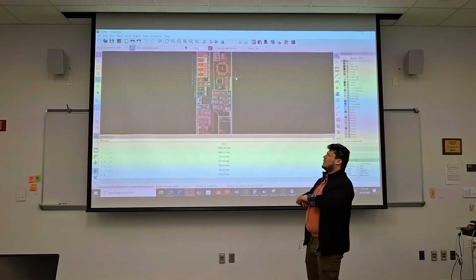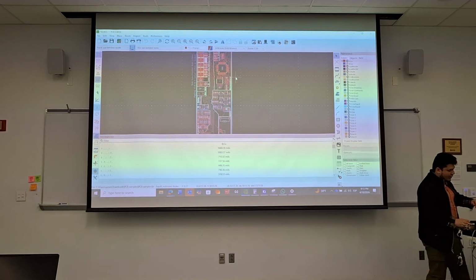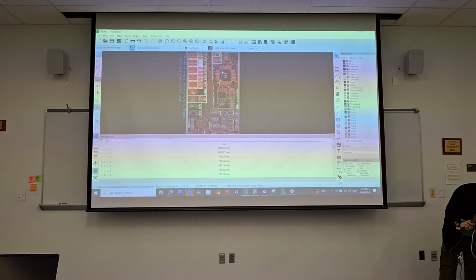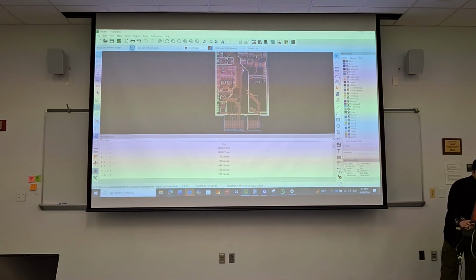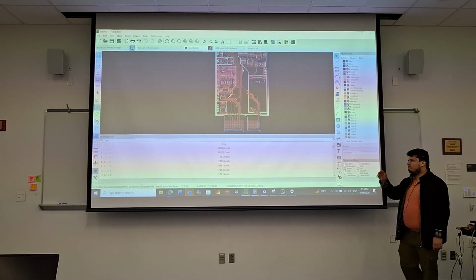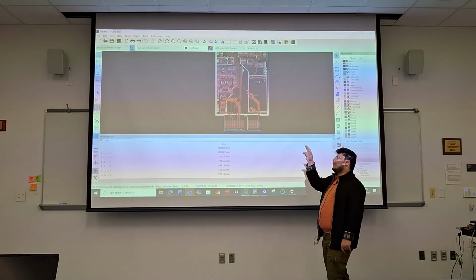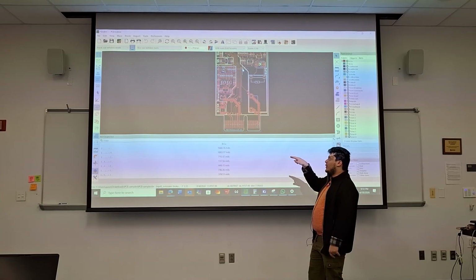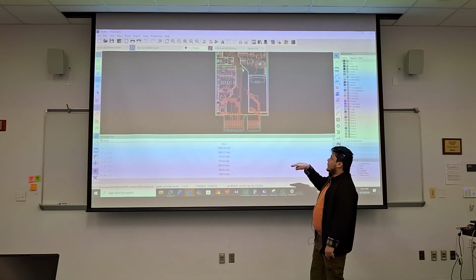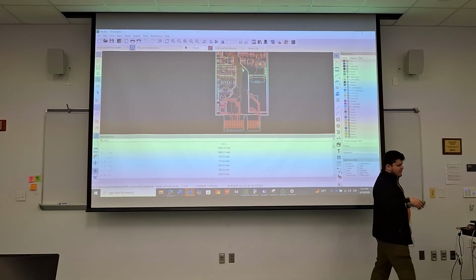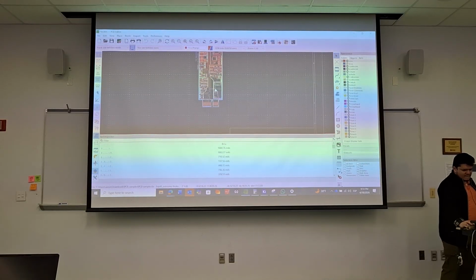Or, because you only have one type of power, right? Or how many powers do you have on this? Just one. Yeah, you're 5 volt. I mean, you could also do the top layer, ground layer, power, and then your lower speed digital stuff referencing the power. How big is this card? Like 7 inches?